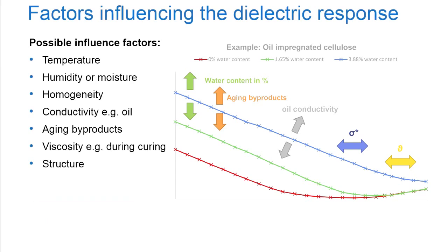Only if the curve is completely measured and other parameters like epsilon or permittivity are analyzed, a separation of the effects and a correct moisture assessment is possible. Attention! Dielectric parameters are also influenced by the material itself and the sample dimension.